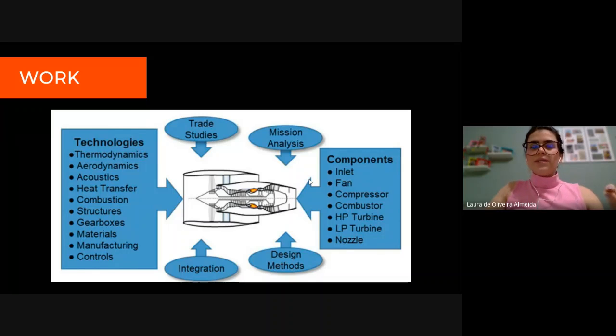Design tool choices fall into two general categories: internal and external design. Internal design contains aerodynamic, thermal, and structural constraints. External design limits are those imposed upon a design organization from outside the company, such as legislative restrictions and protection of the environment. Then, a detailed study of the components and stages inside the jet engine was done, such as low pressure compression, high pressure compression, combustion chamber, and high pressure turbine and low pressure turbine.